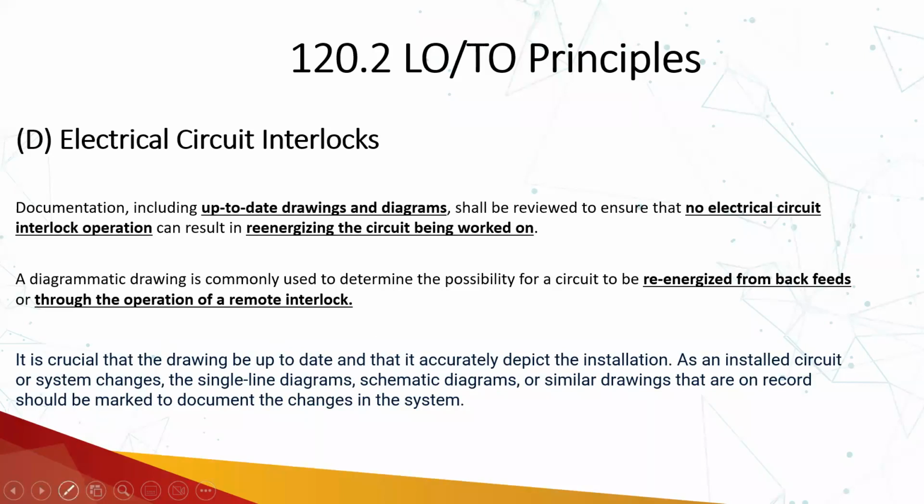It is crucial that the drawing be up to date and accurately depict the installation. As an installed circuit or system changes, the single line diagram, schematic diagrams, or similar drawings that are on record should be marked to document the changes in the system.